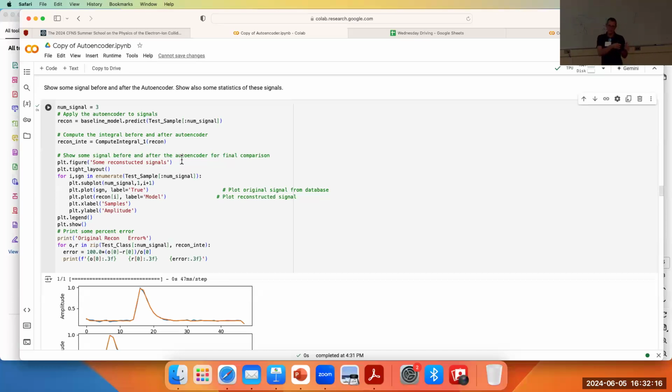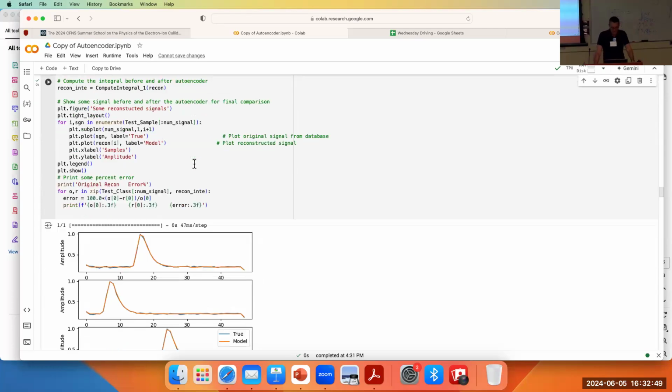I'm going to calculate the integral at the very beginning on the true sample and move this information up to the end. Okay, and I keep the waveform just as extra information. So I calculate the charge with a minimal error. In that respect I'm cheating a little bit, because I want to have a good integral just as an indication that my waveform is correctly reproduced, but that is not what I use in real life. I want to use as much as I can the original information, so the charge calculated from the original waveform. That is just a number, so it's not heavy to move along my procedure.